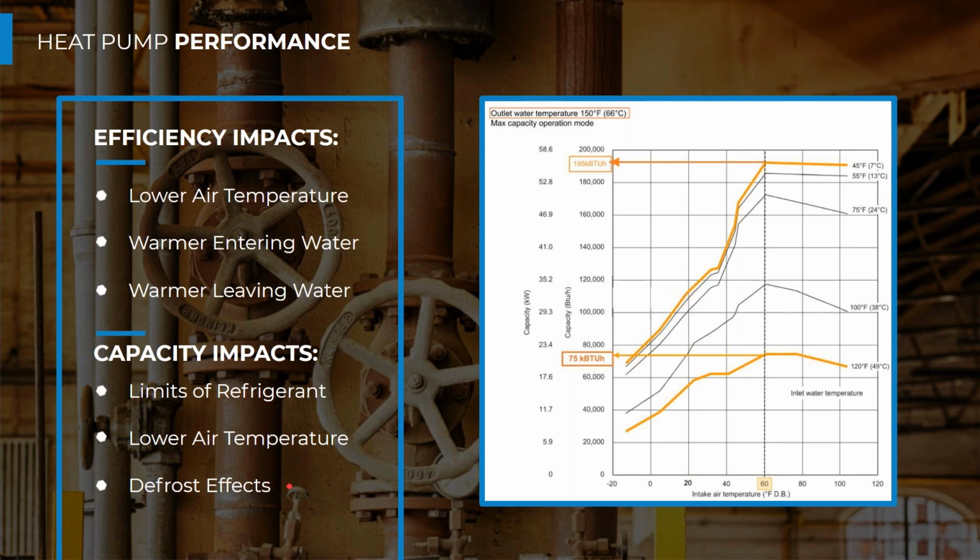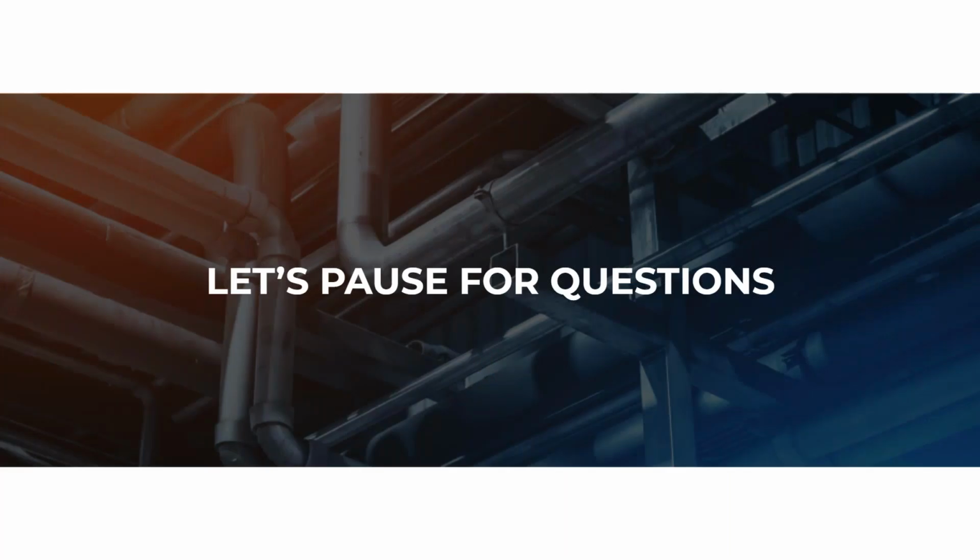And then defrost effects, we'll talk about that a little bit later when we get to sizing, but these heat pumps typically need to defrost when the ambient air gets cool. And so we need to take that into account because we're typically not generating heat or putting heat into those storage tanks when the heat pump's in defrost. So that's going to lower our capacity over the course of a day. So we can pause for questions here before we move on.